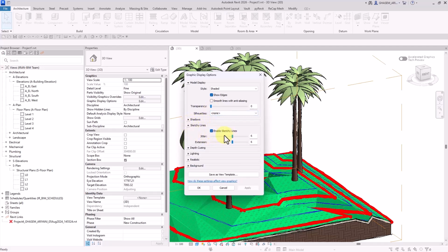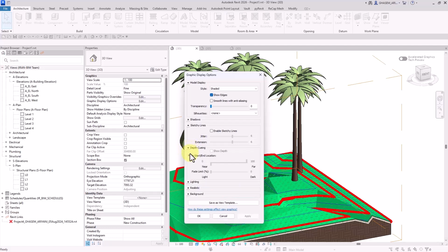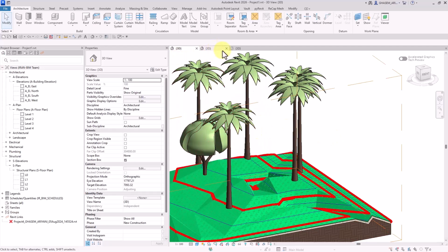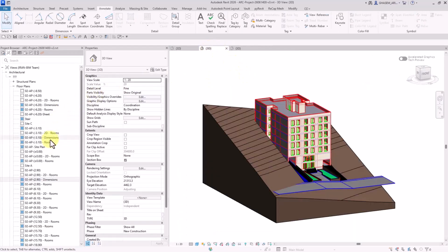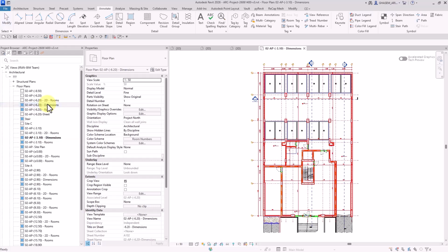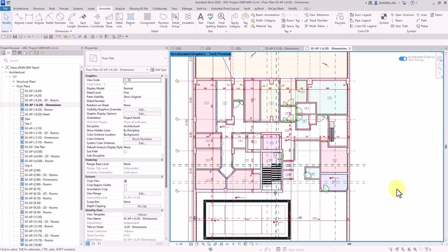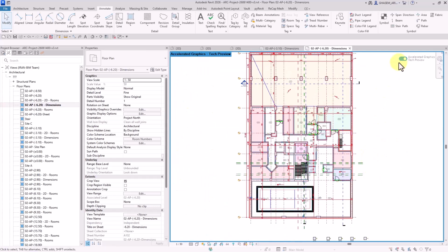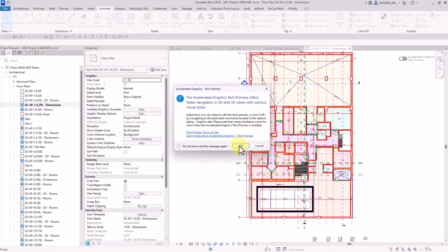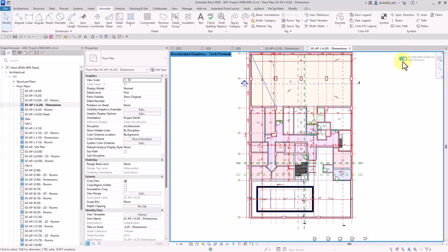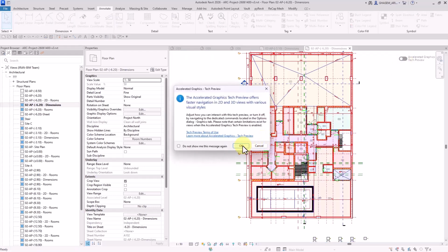What else? I guess we also have a problem or face a limitation if we use depth queuing, guys. By the way, we only use this item in an architectural discipline for sections and views. Nonetheless, depth queuing won't be supported either. And also, view range cannot be displayed quite properly here as well. For example, we got a view range here. If I activate the item, the view range won't be functioning properly. Like some of the items and elements that are set outside the view range might be displayed as well.